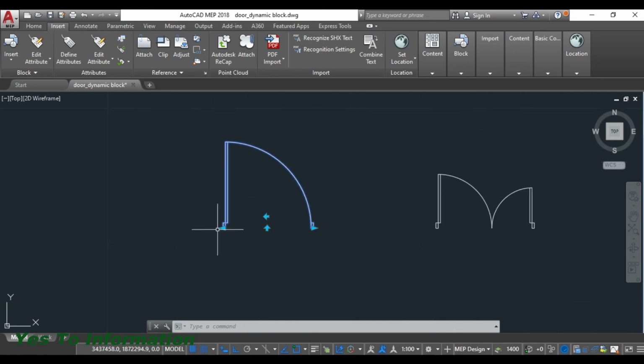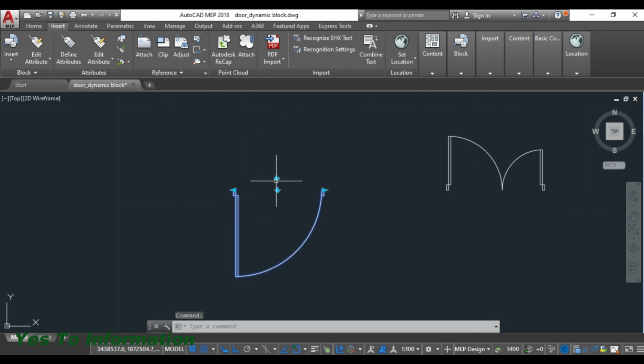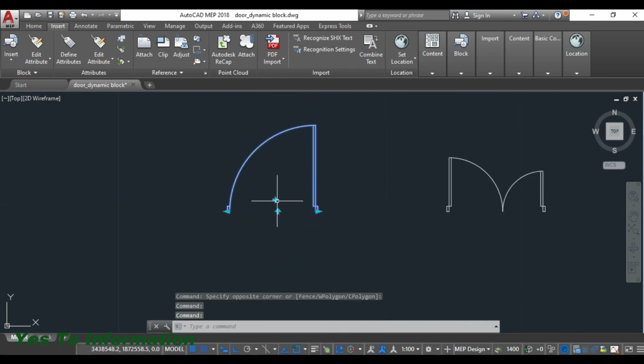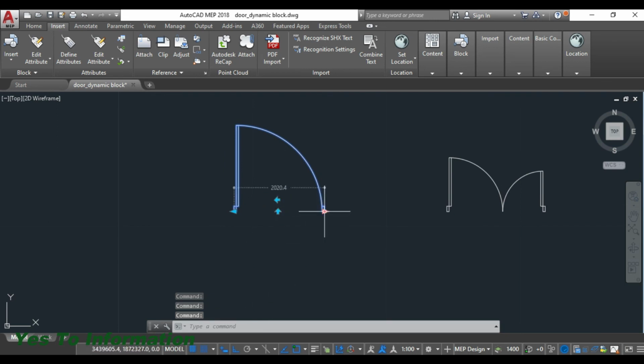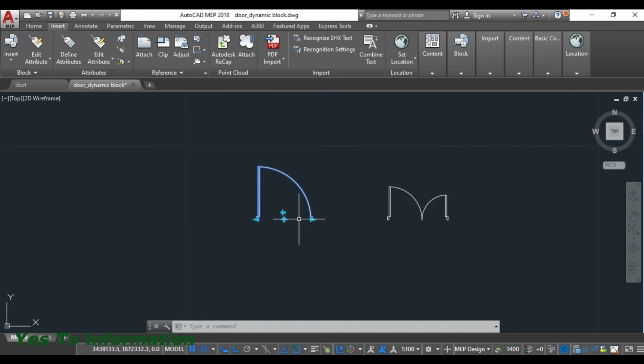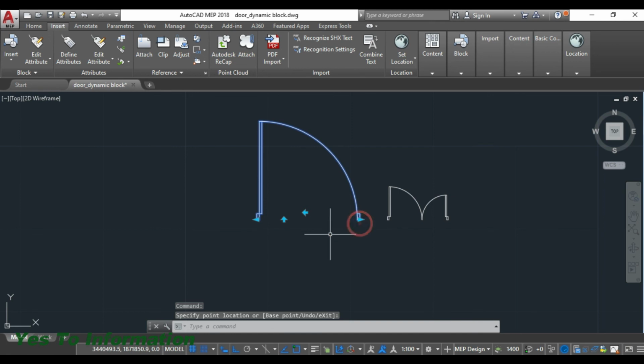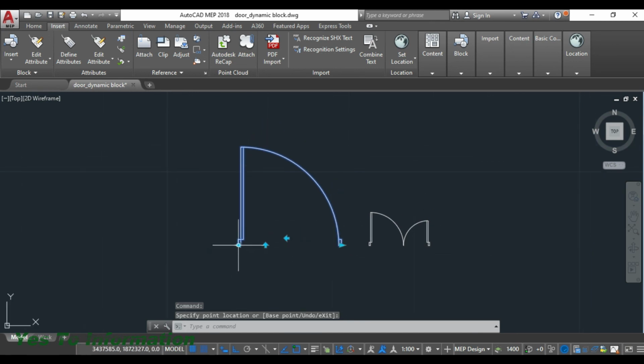If you click it, you can see grips here. These grips are actually parameters which make this block dynamic. If you click this upright flip parameter, it mirrors our block. You can flip it in any direction. You can make it small and big with this distance linear parameter after applying the scaling action. Do try out other parameters and add actions to these parameters also, to explore new things about the dynamic block.